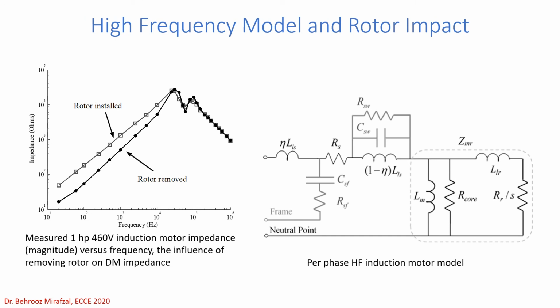Here we can see the proposed model for high frequency studies of induction machines, mainly induction motors. And as you can see, the rotor circuit and magnetizing circuit are the same as what we have in the low frequency model, the standard one. We only touch the stator side. And the reason is that the rotor has no impact on the model at high frequencies.